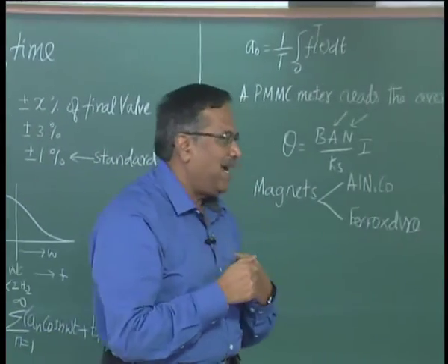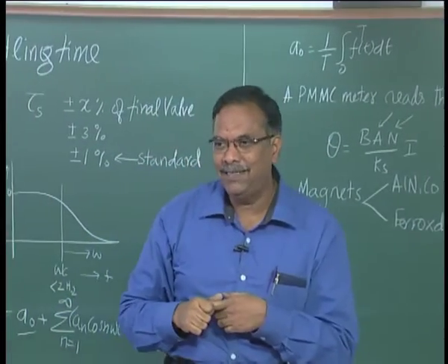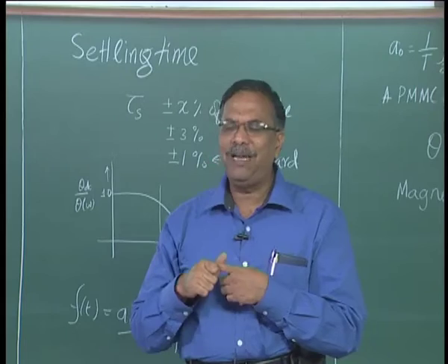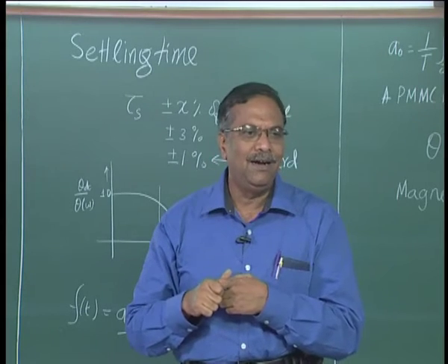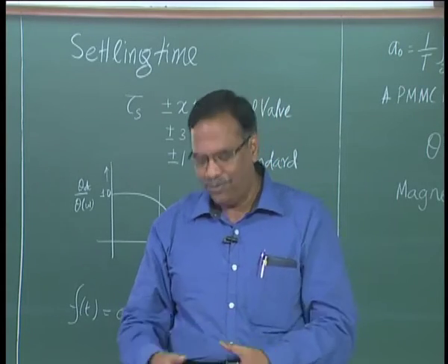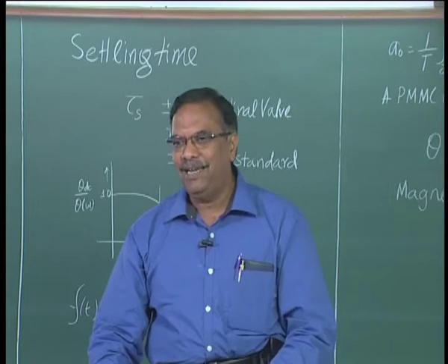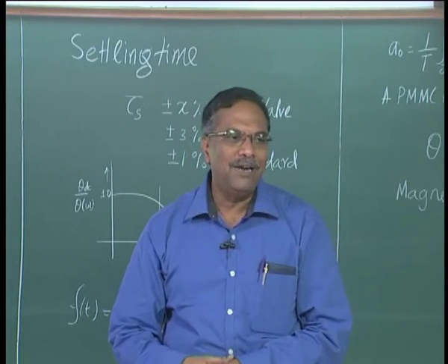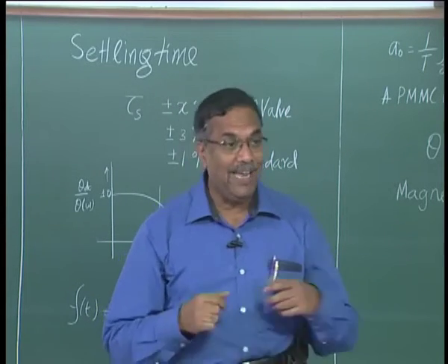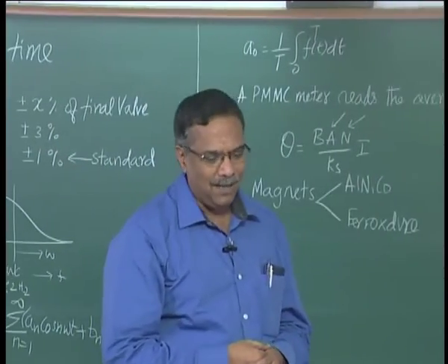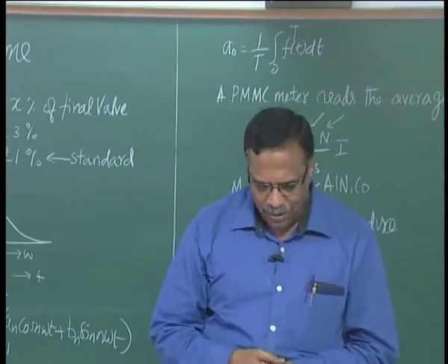These are called taut band suspensions, and the taut band suspensions were very fragile in nature. You keep the meter with the kind of acceleration, and the taut band will break. So you will have to take care if it is a taut band suspension meter.